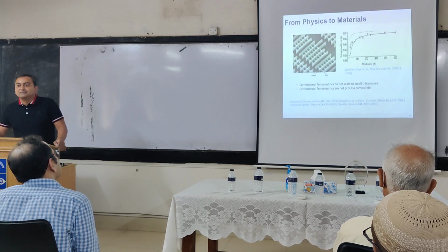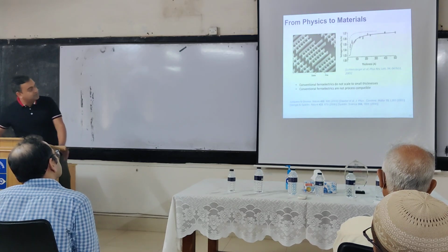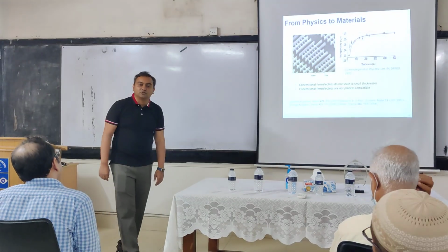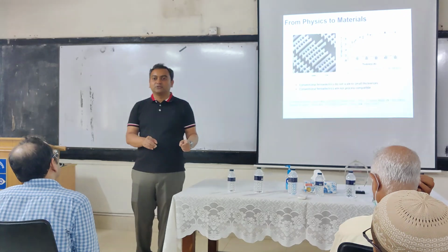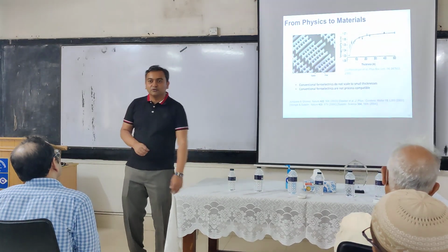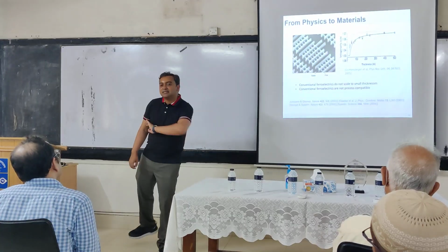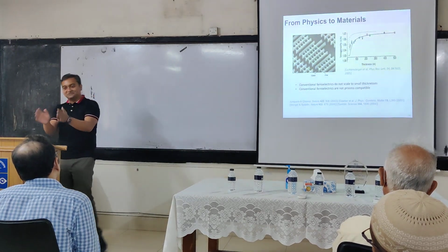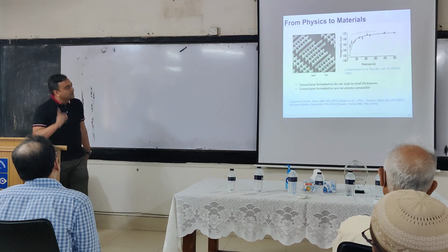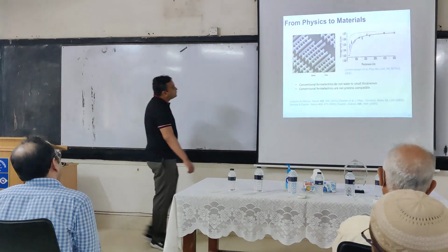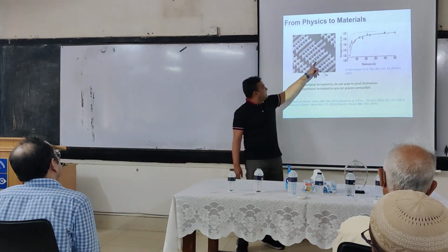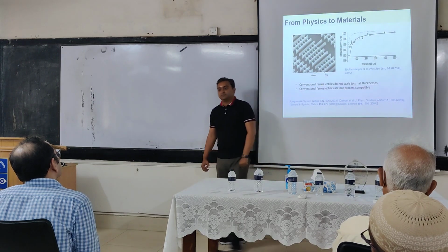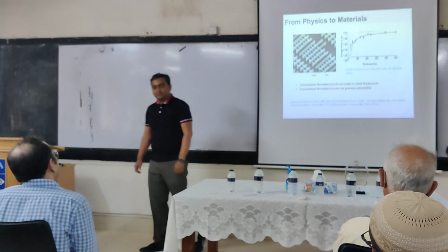So Intel, like a month ago at the VLSI Symposium, showed 4 nanometers. 4 nanometers does not mean the channel length is 4 nanometers. I hope all of you know that. 4 nanometer has nothing to do with anything that is 4 nanometers. Nothing in the transistor is actually 4 nanometers. It's just a name. But the point is, for the 4 nanometer node, the gap between the fins is 29 nanometers.